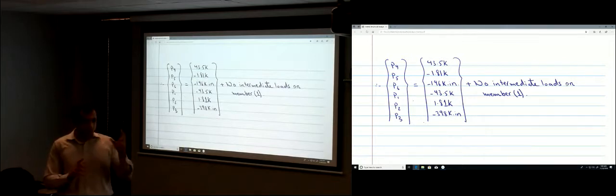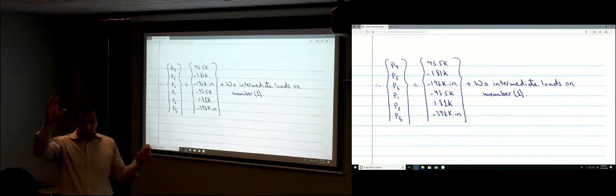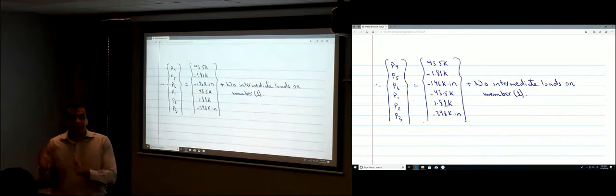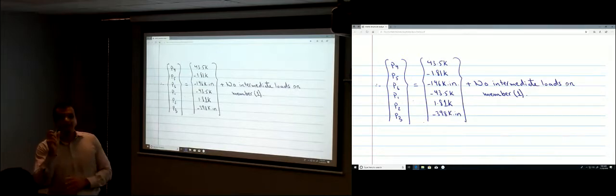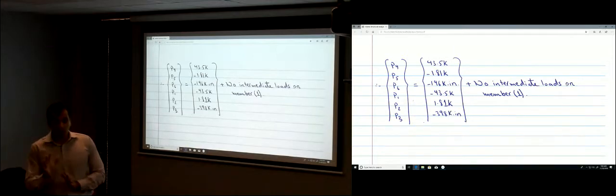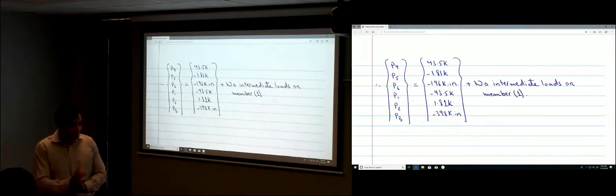P are 6 forces. 3 forces at the start, 3 internal forces at the end of the member, right? Equals K, just substitute K local, multiplied by U. You already know U, but in the global direction. You only have to transform it from the global direction to the local direction. Okay? How can you do this?